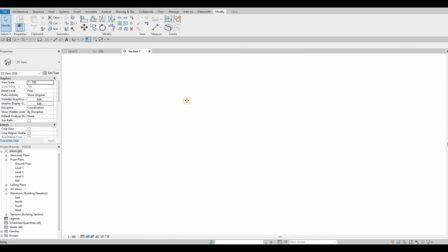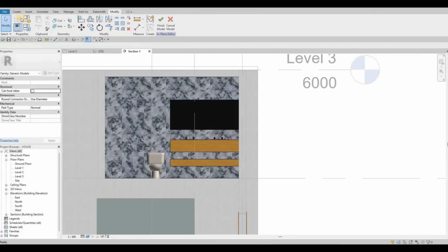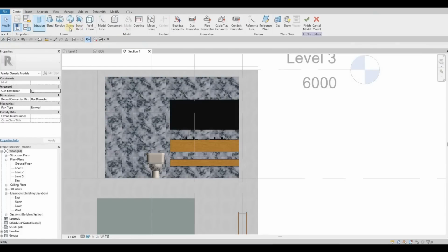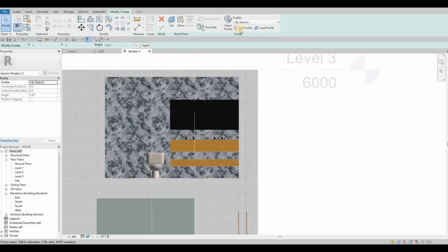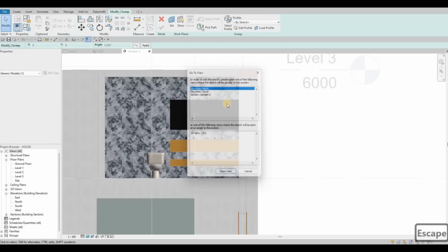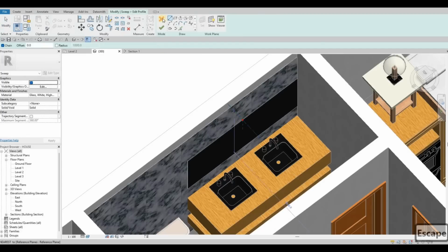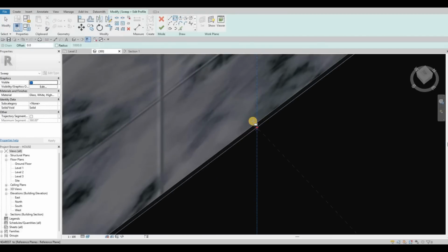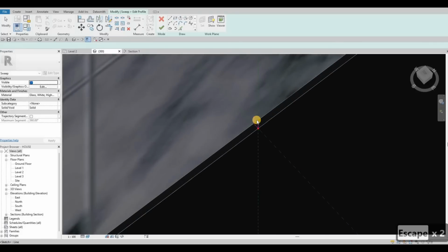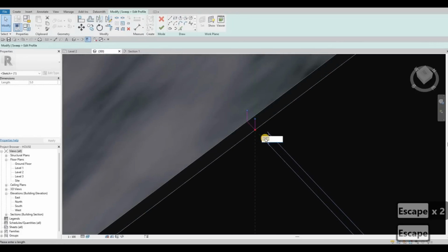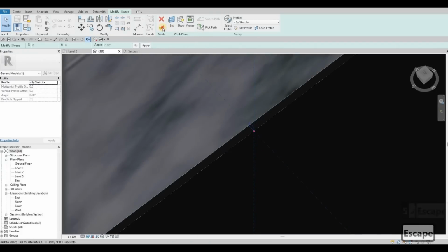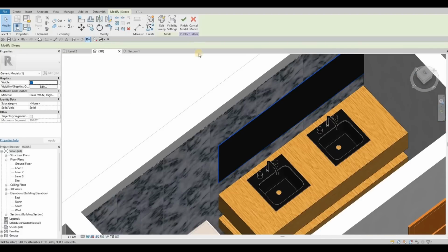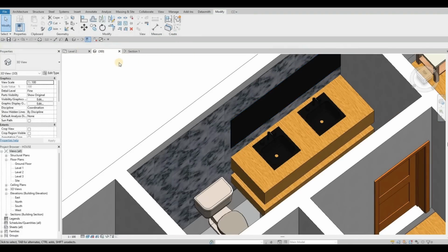We have mirror, and then of course the light. So I'm going to add that one as well. So create, sweep, pick path. We're gonna select this path right here. Click finish, and then edit. Let's check this one. I'm going to create right there 5 and then 5, and then for the material, luminance is good, and then click finish and then finish. So we have that light there, so that's good.